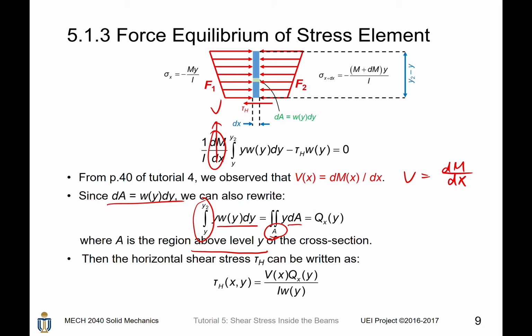Another observation is that this integral is rather familiar, right? We introduced in tutorial 0 that it is the first moment of area with respect to the horizontal axis, which is Qx of y. So in the later stage, you will do some examples where you find the first moment of area above a certain level of y for some problems. So you may see those things later.